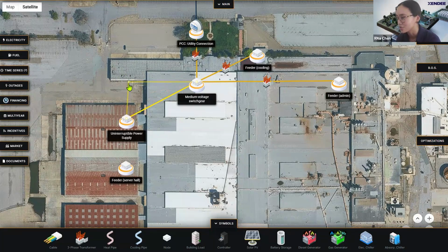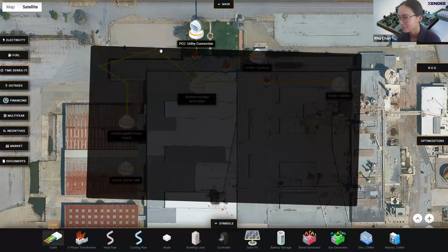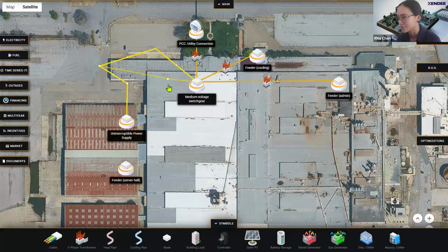connection dots to map it out more realistically. So if your cable is really winding or wraps around your project, you can do that. As you do this and change your cable length, if you click back on it and look at your calculated cable length, it's going to automatically update based on the location estimates. Okay, I'm going to change this back to my previous layout.